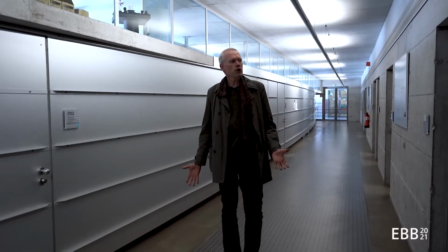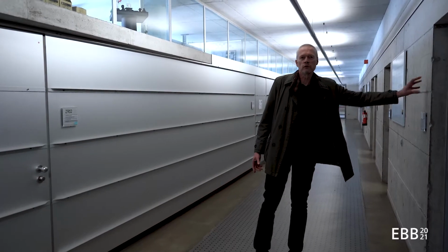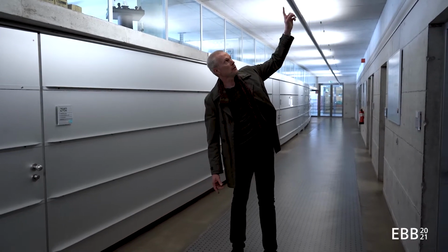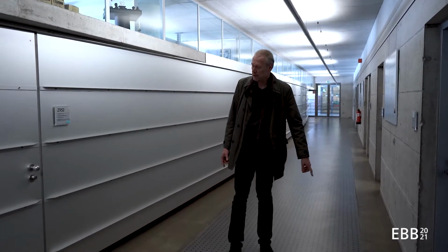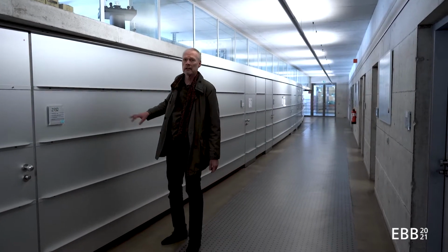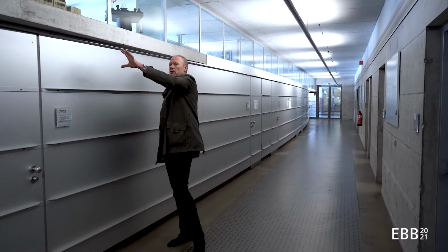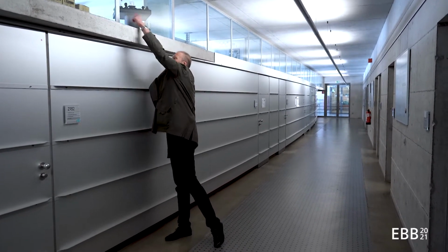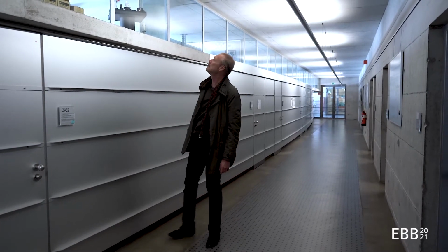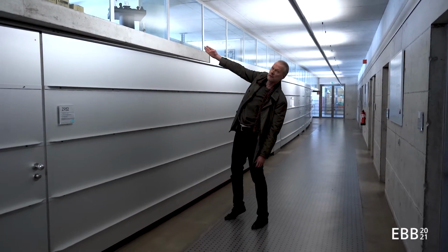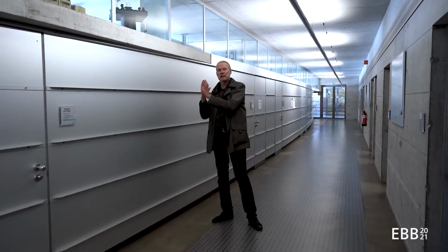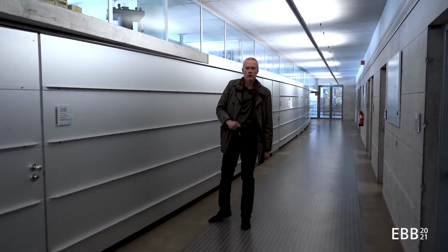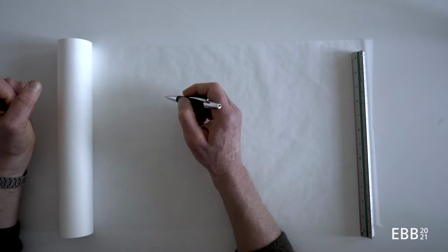So here I'm standing in a corridor, and you can see that one of these 2 walls must be load bearing, because it's in concrete. It's linked to the ceiling and it's linked to the floor, while the other one is supported by a horizontal beam in reinforced concrete. And then you have metal parts on top of it and in the lower part. In certain areas you have the interior walls meeting this non-load bearing separation from the offices to the corridor. So we have to do with different solutions.